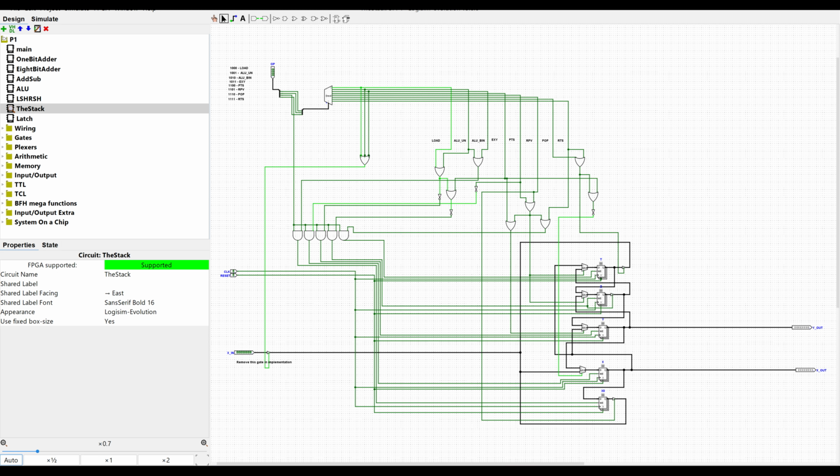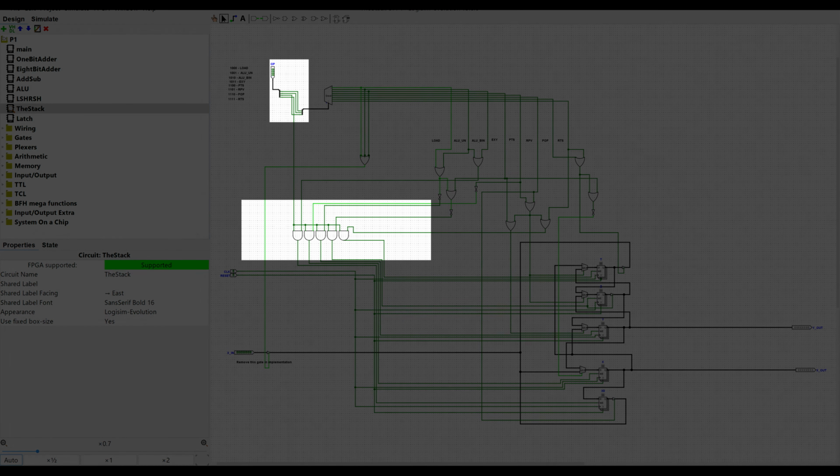And for the ALU it's not important, because for the ALU you don't store any data. You update signals on the input, you get the update on the output. For the stack you actually sample the values and store them, which means you need a special command like don't update the value. Instead of sending 3 bits into my decoder, I will send 4 bits, but the fourth will be used to control a set of AND gates that will either enable or disable the write enable pins.